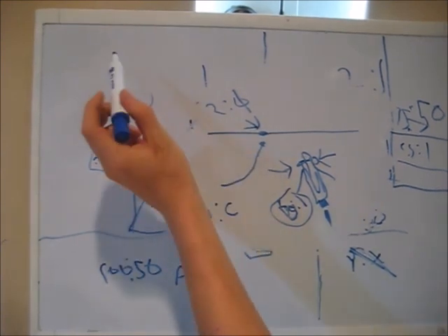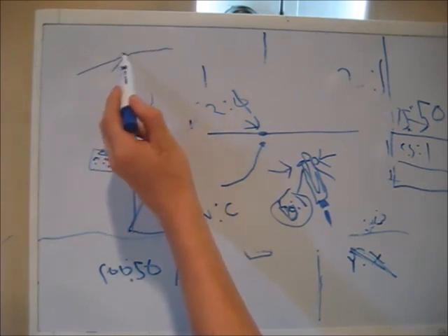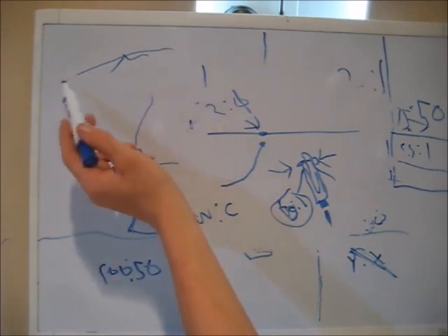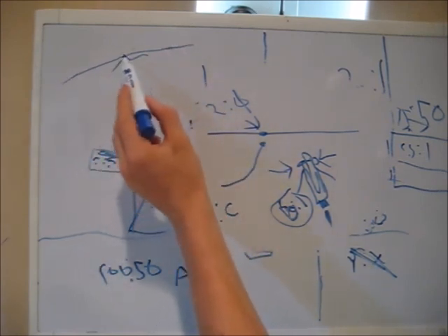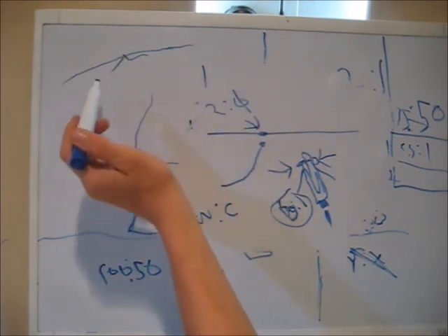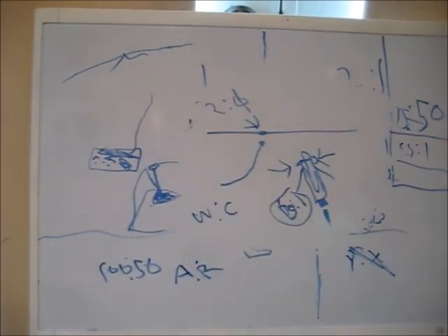So if you have an antenna that has a steady 2-to-1 SWR, now this could be for several reasons. It might not be that it's 100 ohms, but if you get an antenna that has a steady 100 ohms across your whole band, then you can just get a 2-to-1 balun that'll downstep it and divide it by 2, resulting in a perfect 50 ohm match. So that's sort of how baluns work.